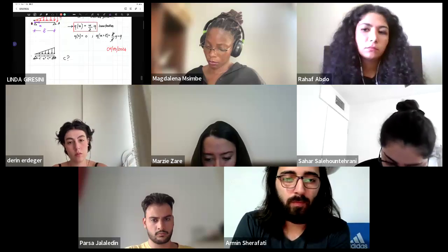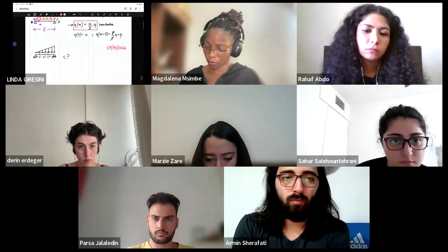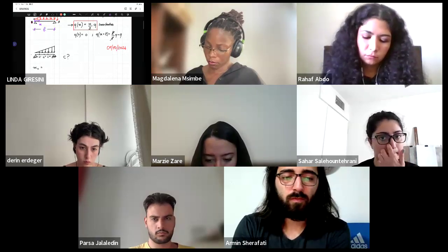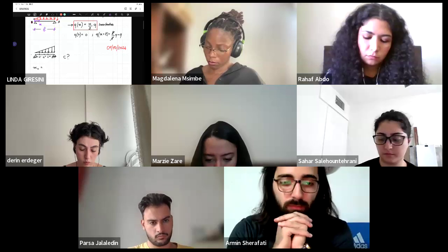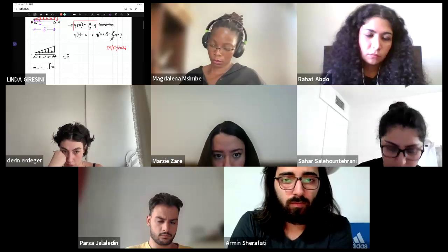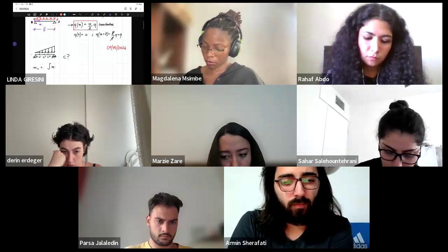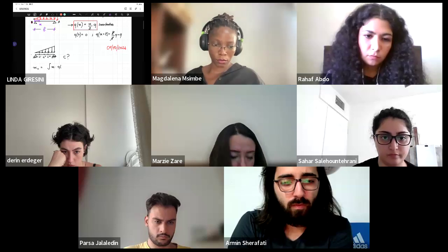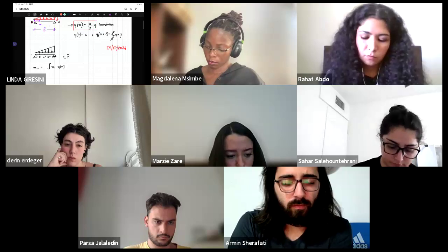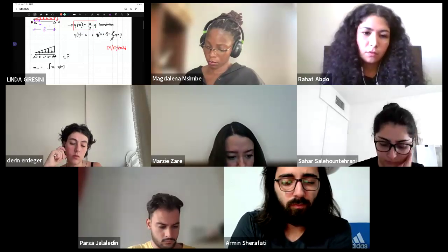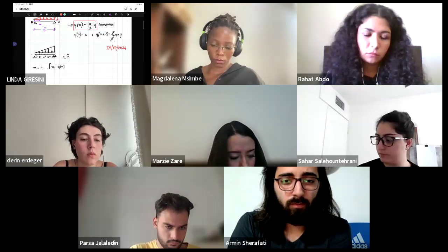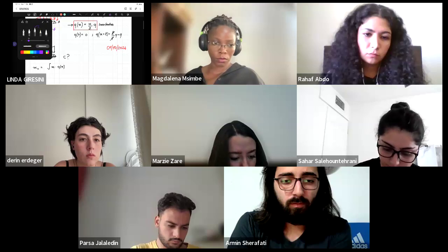So what is the real position of C? First of all, we need to write that xc is equal to the integral of what? x, the generic x, times Q(x). So it's like writing down the static moment. So on the numerator of this formula, we have the static moment with respect to the y-axis.